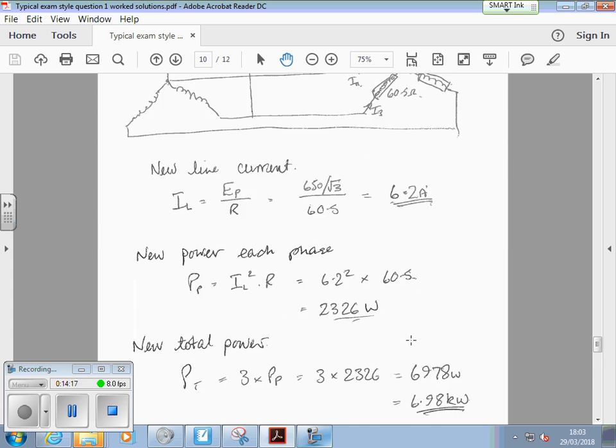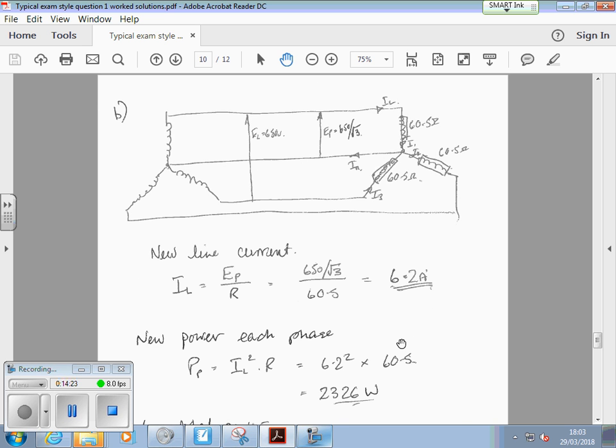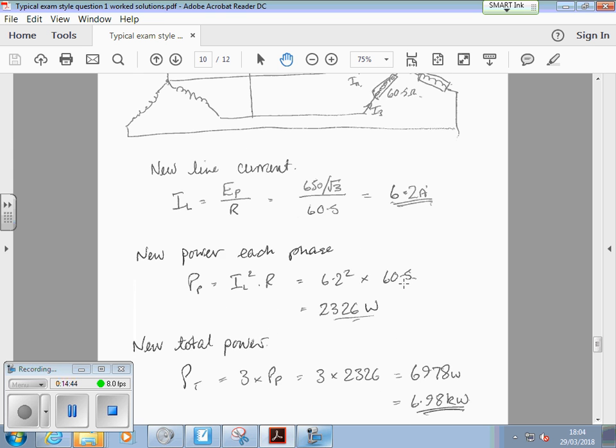When you connect the same load in star as opposed to delta, it's still quite plain that the line current, because line current and phase current are the same, is nowhere near the same as that 18.6 amps. In fact, it's a third of it. All right?